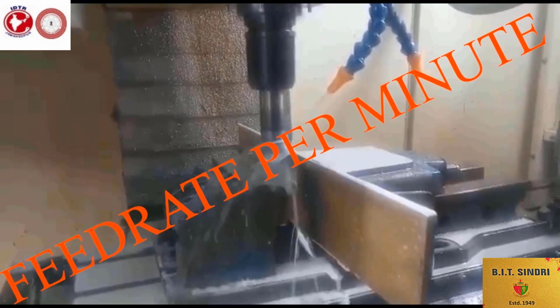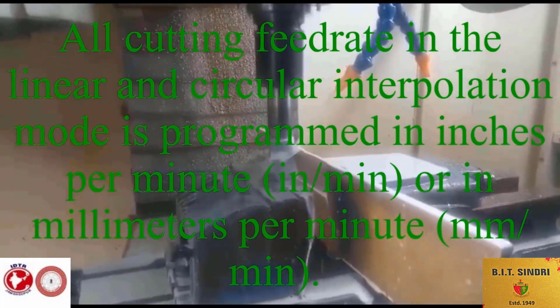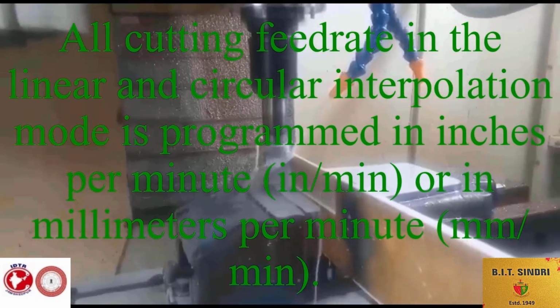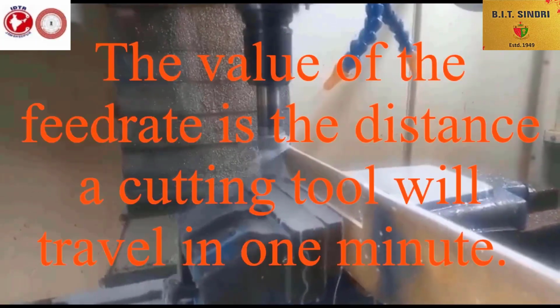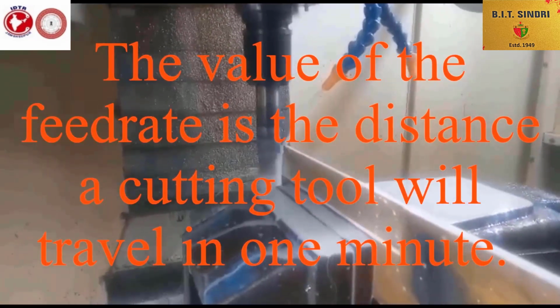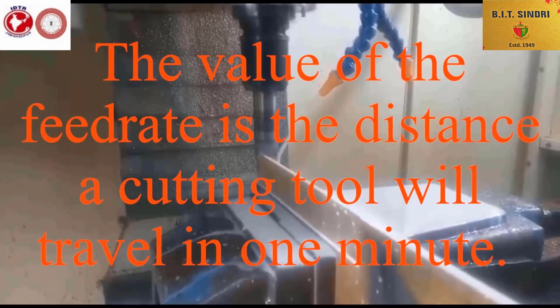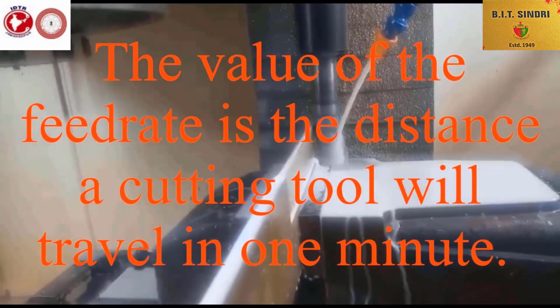So, feed per minute. For milling applications, all cutting feed rates in the linear and circular interpolation modes are programmed in inch per minute or millimeter per minute. The value of the feed rate is the distance a cutting tool will travel in one minute. This value is modal and is cancelled only by another F address word.